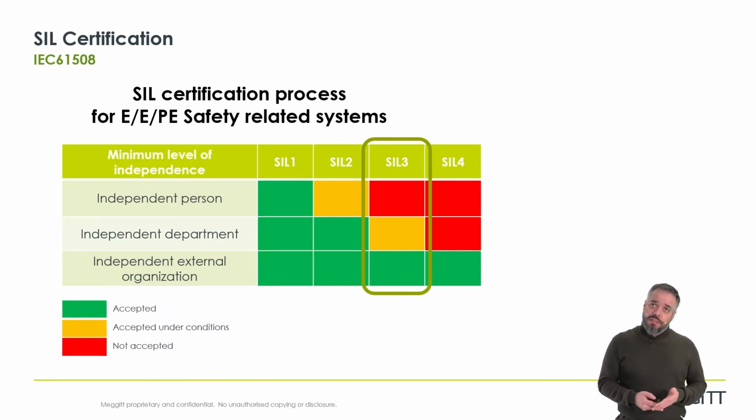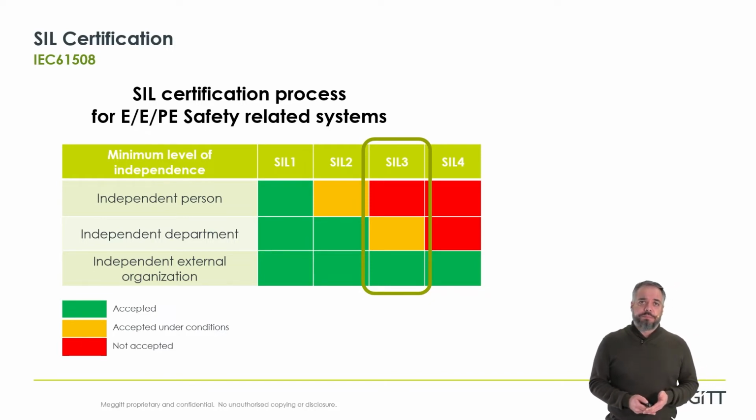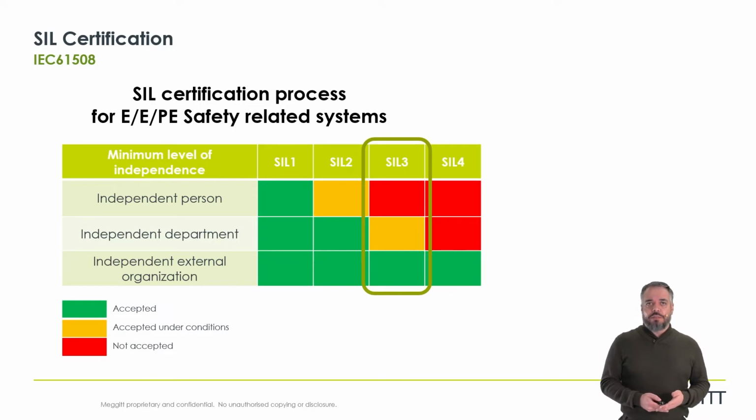However, if the safety system is simple enough, or if there is proved expertise, the standard allows us, in this case and under justified basis, to do the assessment with an independent department within the company. Note that here we are talking about the assessment part of the certification. The SIL certificate itself can only be issued by a certified body.